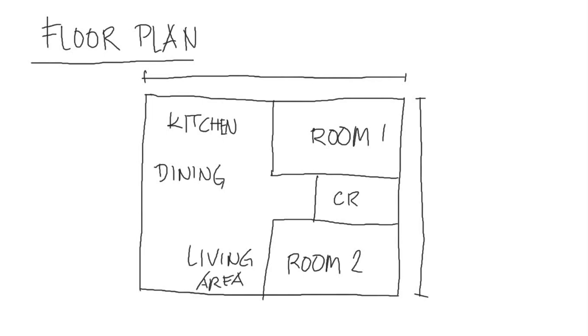After you have done making the floor plan, of course, don't forget to draw on scale. You can choose 1 to 100, or 1 to 1000, or 1 to 10, depending upon your chosen scale. But you should draw with scale. So don't draw like you are just sketching without any specific dimensions to follow. Since you will draw your plans in the AutoCAD, you should specify the units that you will be using and the scale that you will be using.